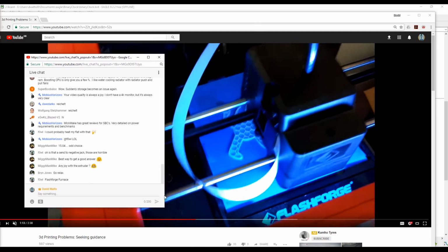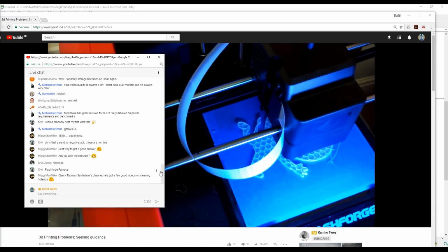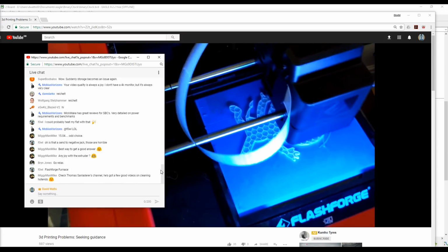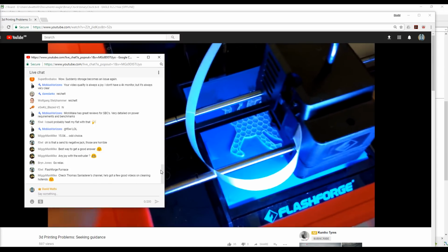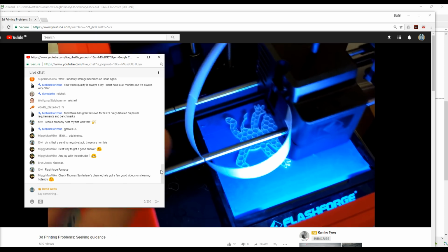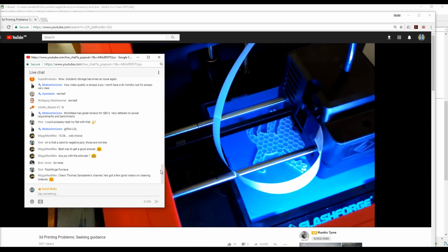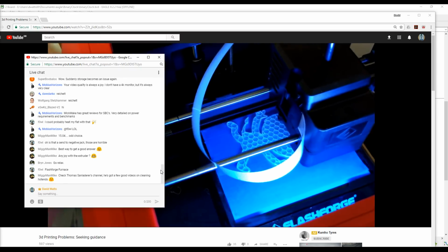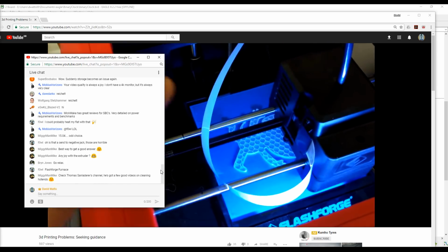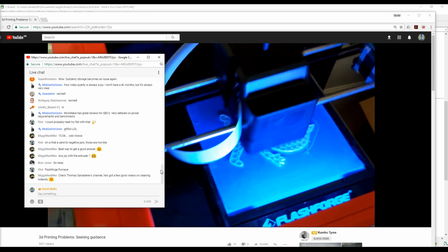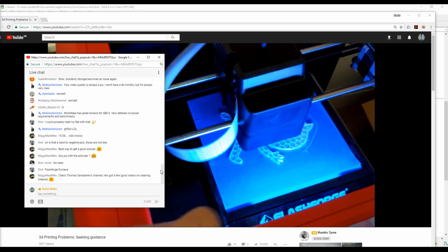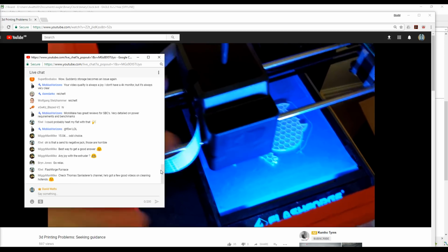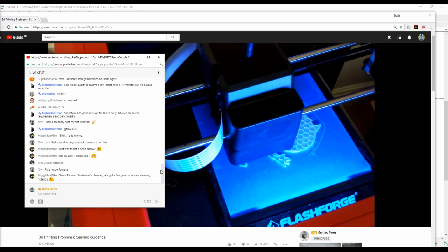So yeah, so many times the level has been the problem, but in this scenario, what happened was this filament that's printing now, you can actually see on that video that the infill layers are looking all right. Now this is printing at a higher temperature. I just changed the bed level, but the thing is, I was changing more than one thing at a time. I wasn't removing one of these potential issues at a time, because I'm just really impatient. 3D printing is a long process anyway, so it just takes ages.